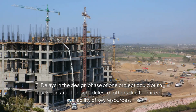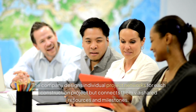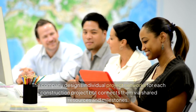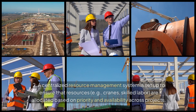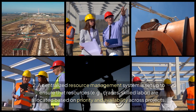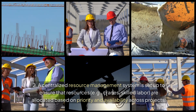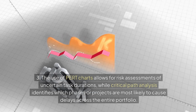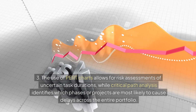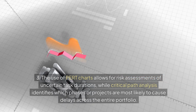of key resources. Solutions. The company designs individual project networks for each construction project but connects them via shared resources and milestones. 1. These milestones trigger the start of activities in subsequent projects or phases. 2. A centralized resource management system is set up to ensure that resources, e.g., cranes, skilled labor, are allocated based on priority and availability across projects. 3. The use of PERT charts allows for risk assessments of uncertain task durations, while critical path analysis identifies which phases or projects are most likely to cause delays across the entire portfolio.